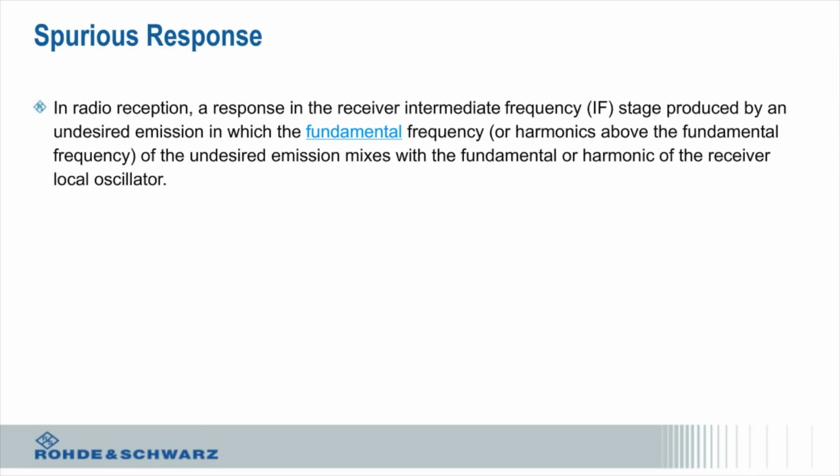But that mixer puts out spurs, or unwanted signals, that we need to be aware of. When we are receiving a signal, we really want to look at the desired input signal and not the stuff generated by the receiver itself, or things that are coming from somewhere else that we're not interested in listening to. So one of the key characteristics, particularly dealing with mixers, is the spurious response.